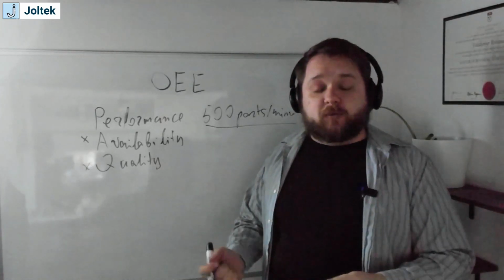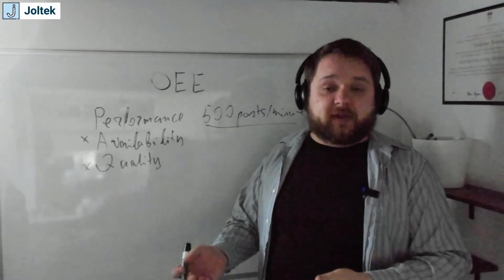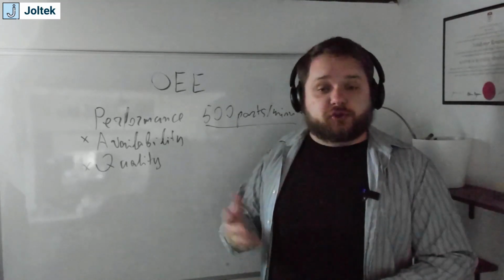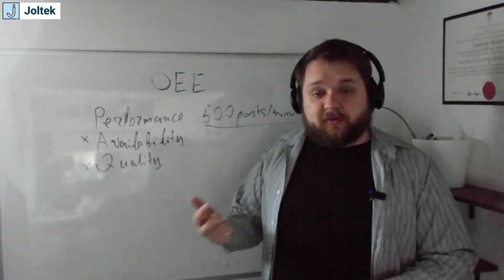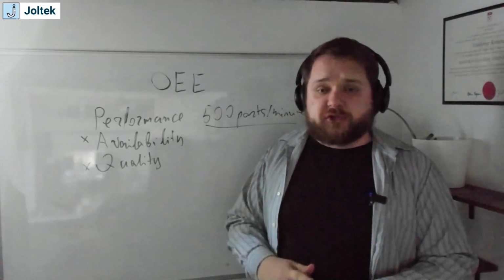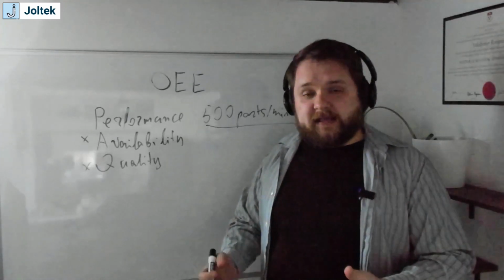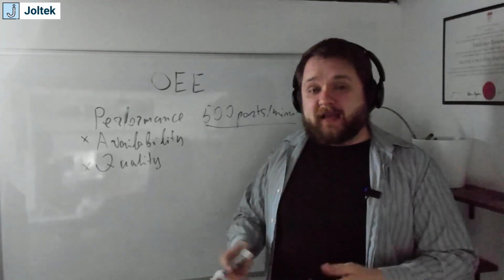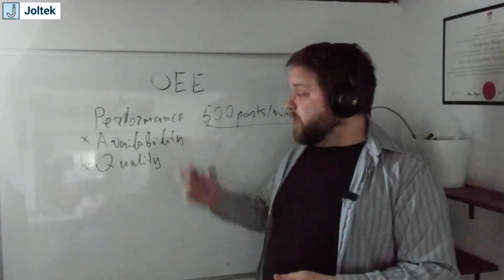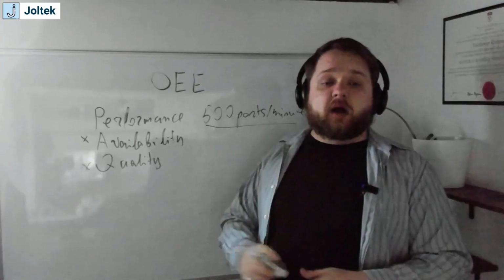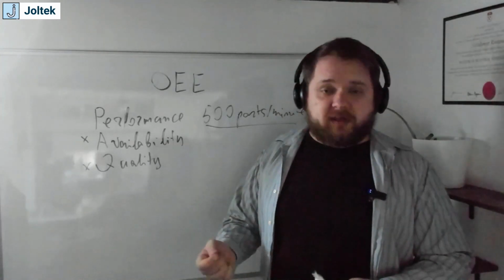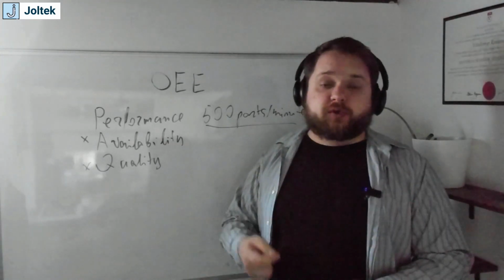Some of them will utilize the tags available already on the PLC side. Those could be your cycles. Those again could be the photo eyes at the exit, at the entrance, in order to understand the states. And then you're also going to tie in some of the quality and availability data. So availability a lot of times is going to be within the PLC. It's going to be your fault codes. It's going to be your state.